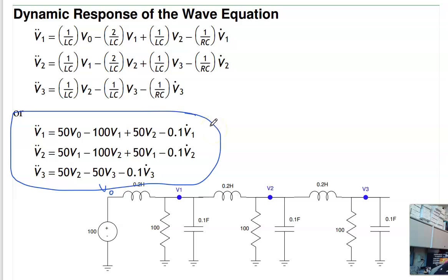Now to solve these, that's a little bit of a trick to solve by hand, but MATLAB's here. With MATLAB, I can solve second-order differential equations. The idea is, just like we did last week, integrate once, I get the first derivative, but now I integrate a second time to get voltage.